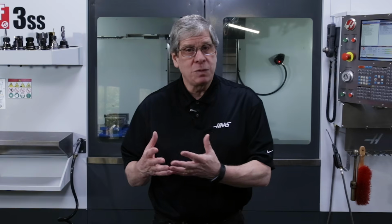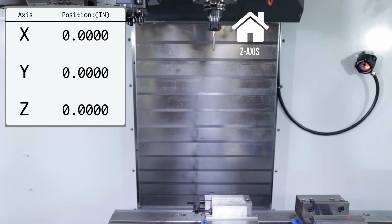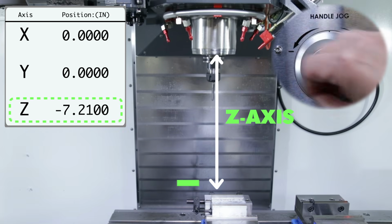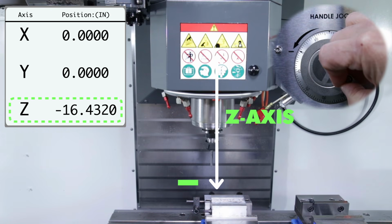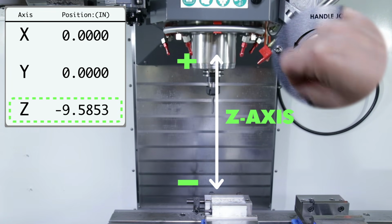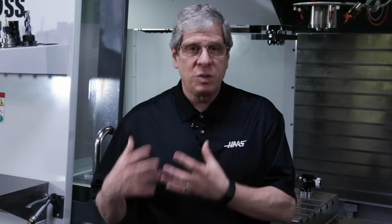And, as you might expect, the z-axis also works the same way. Home position is at the top of travel, and as we move down towards the table, the spindle gets more negative. So, for the z-axis, moving downwards is moving in the negative direction, and upwards is positive. So, we looked at the machine coordinate system, basically the values that tell the machine where the table and spindle are relative to each other.